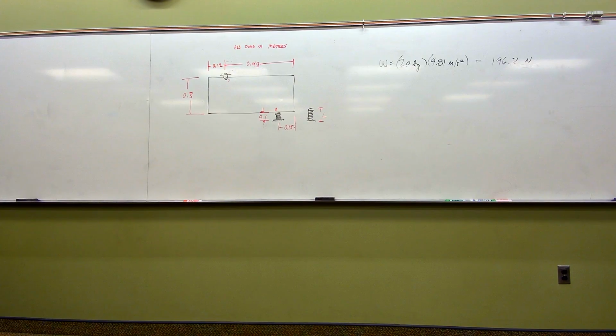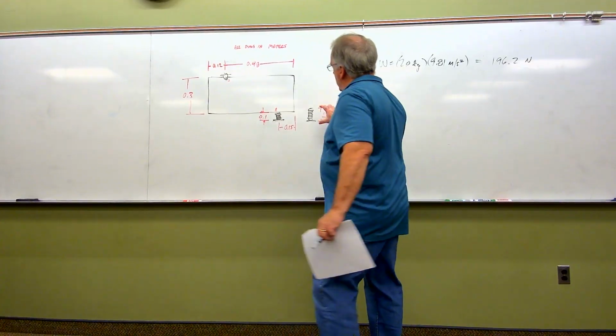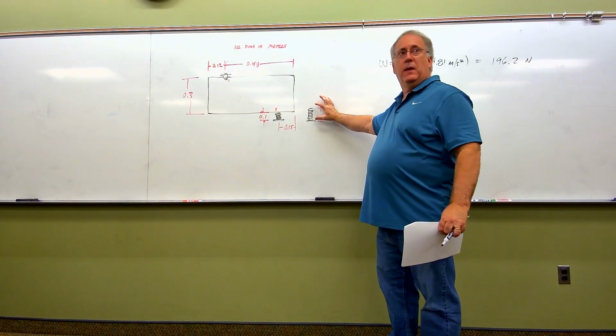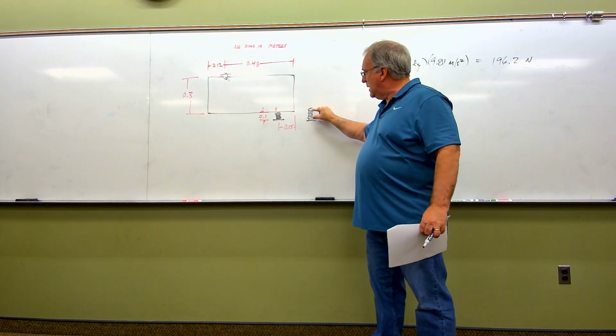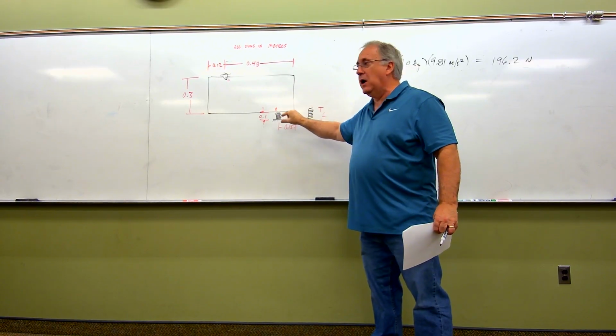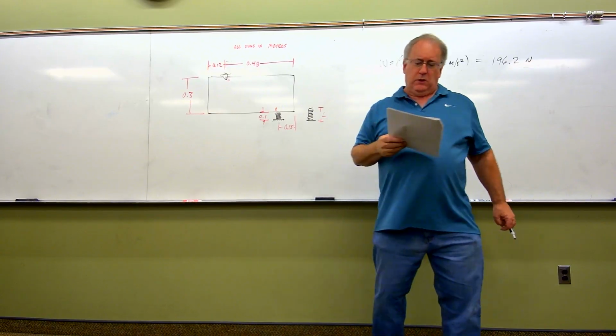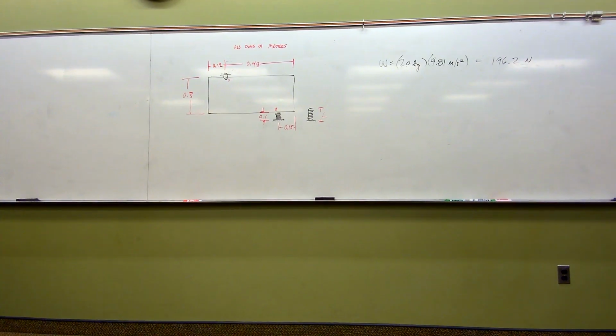So we've got an ideal pivot at O and a spring which must be compressed prior to being slipped into place at point A. What we're saying here is there is a spring with an original length, and in order for that spring to support this plate, it has to be compressed before it gets put in under here at point A. If the modulus of the spring K is equal to 2 kilonewtons per meter, let's write that down.